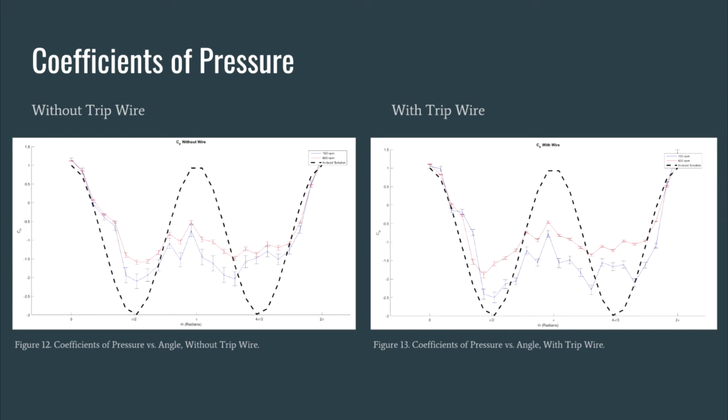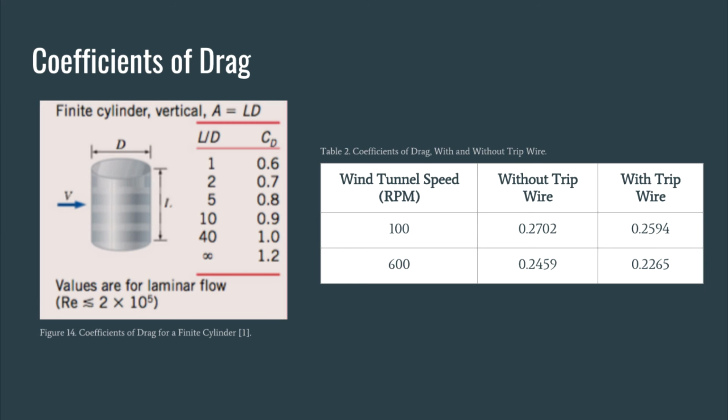The pressure coefficients seem to be much lower behind the cylinder in the tripwire case because the flow separation earlier on in the cylinder creates bigger vortices behind the cylinder due to its blunt body. Since the length of the cylinder used in testing reached both walls of the test section, it can be approximated as a cylinder of infinite length.